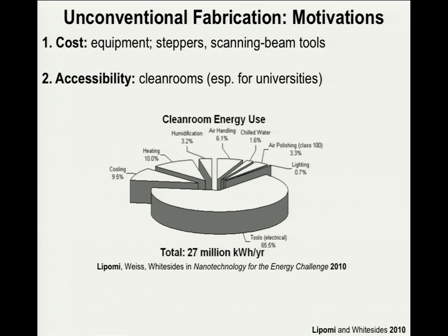Clean room equipment tends to be under high vacuum or high temperature, something that requires pumps and heating elements and thermionic emission of electrons, all very high current, high voltage equipment. And then the balance of it was on environmental controls. In industry, a fab will actually have a reverse energy footprint, where the air handling, air conditioning and air filtration will take up about 2/3 of this pie. But in academics, it's about like this.